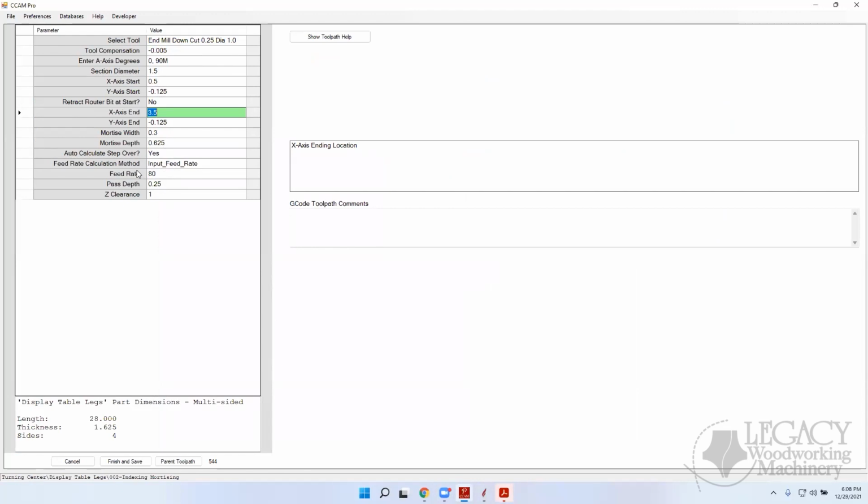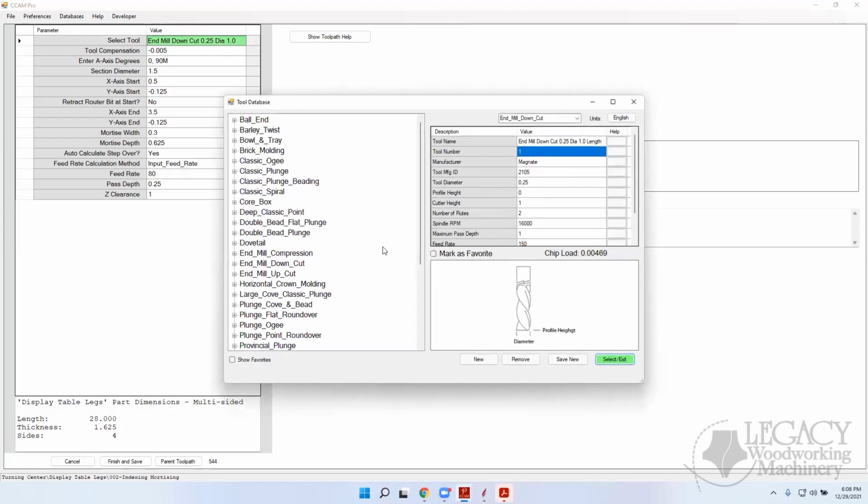I don't see a Z-axis plunge feed rate control. This might be the same feed control on all passes, Z-axis and the linears as well. Mike, if you're still in, maybe you could clarify that. I didn't notice if it was plunging at 80 inches a minute, but it was cutting everything else. In the tool, there is a feed rate and a plunge feed rate. So I'm just wondering if it stays with the default plunge feed rate.